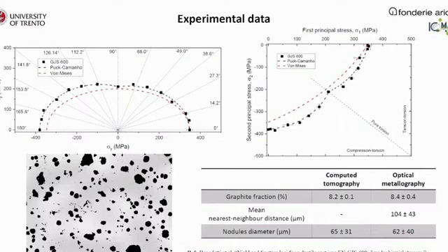So basically, as you can see here in these two graphs, as long as biaxial loading is imposed, the yield strength of the material is higher than that predicted by von Mises. As you can see here, it assumes a cusp-like shape that was found to be well fitted by the criterion proposed by Cazacu, which is a criterion for composite materials, basically.